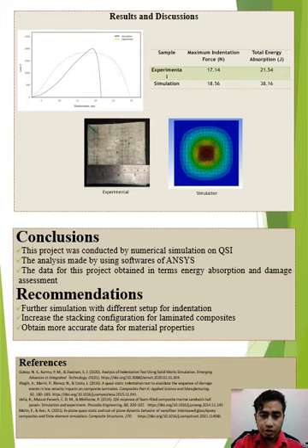When comparing the deformation from experimental with the simulation, we can see the deformation occurs at the center of the laminated composite. However, a bulge can be seen in the experimental result, which distorts the output surface and forms a ring crack. From the simulation, we can see the deformation of the output panels was definitely higher than the experimental.